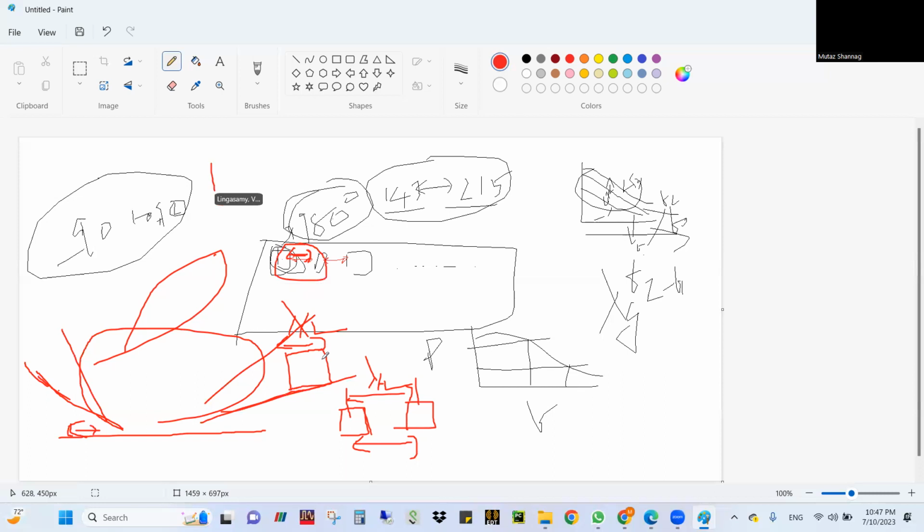For example, you have a unit cell like this, like this. So you have multiple unit cells, right? It has to constructively form a beam. If you are exciting with appropriate weights to steer the beam like this, what will happen is, if you have a huge gap between the unit cells, some unit cell will become an independent radiator, basically. So it will have side lobes, grating lobes also sometimes. So some part of the array contributed for this beam, some part of the array contributed for this beam. So grating lobes will come.